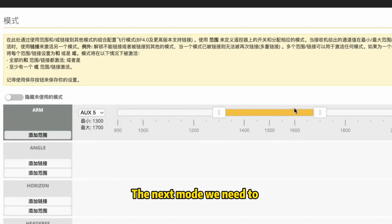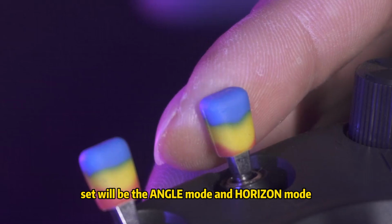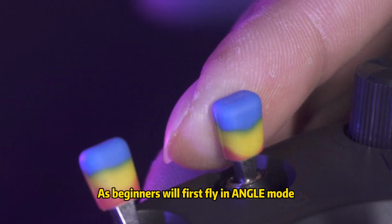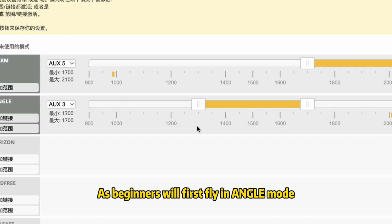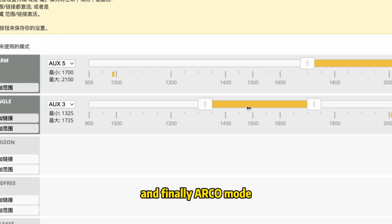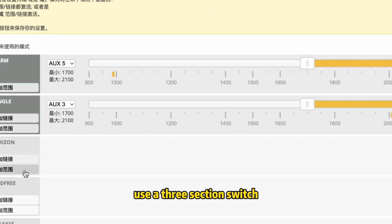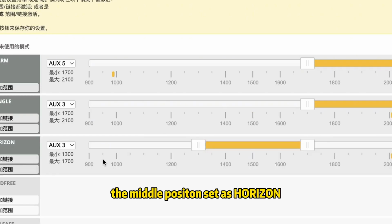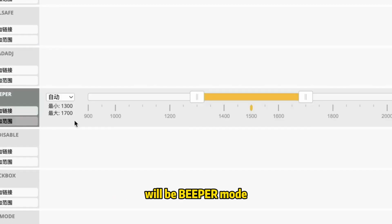The next modes we need to set will be angle mode and horizon mode, as there are different kinds of flight modes. Beginners will first fly in angle mode, then horizon mode, and finally acro mode. Use a 3-position switch, with one position set to angle mode, the middle position set as horizon, and the last position will be acro mode.